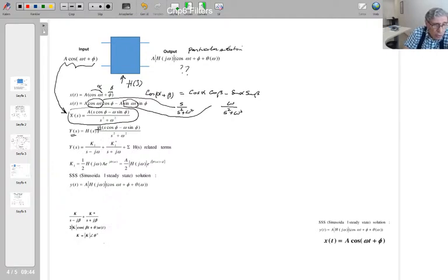So normally, if there is a rational function in S domain, to find out the inverse Laplace transform of this function, you've got to find the characteristic roots. Characteristic roots are the ones coming from the denominator of this H(s) function. So it is included here. And the other two come from that independent source. So for these roots, I'm going to calculate these